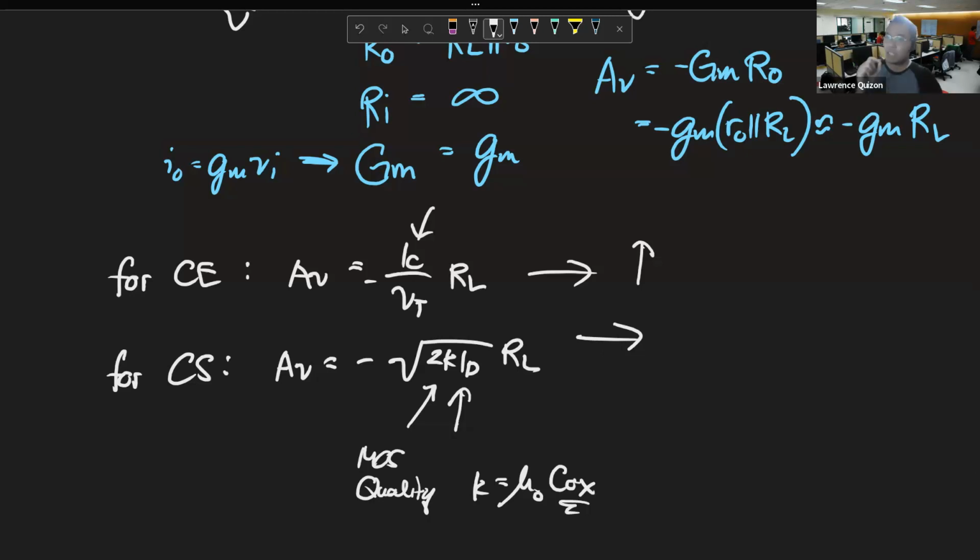When you pick up your transistor, that's it. You have even less control over this. What am I trying to say? For all BJTs, VT will be the same, because it is the thermal voltage, 26 millivolts no matter what. You just have to control the temperature in the room. This thing is possibly different for every MOSFET that you come across, so the BJT is more stable.